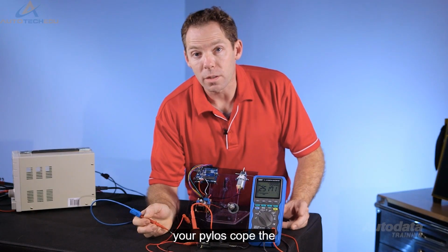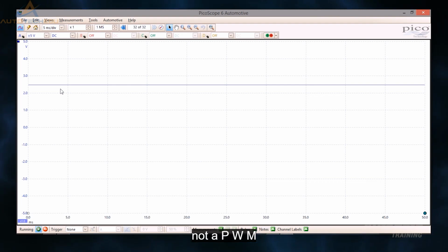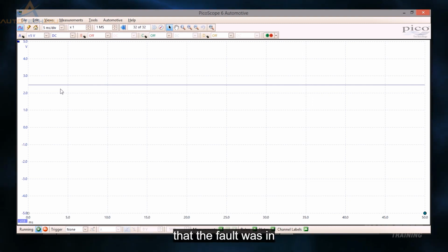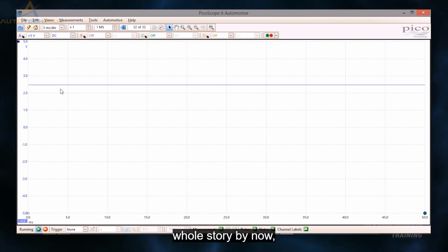Let's have a look with the oscilloscope. The pattern shows that this is not a PWM control, but a steady 2.5 volts. From the multimeter reading, it could be assumed that the fault was in the motor. This would be incorrect. The actual fault is a short to voltage. The oscilloscope told the whole story.